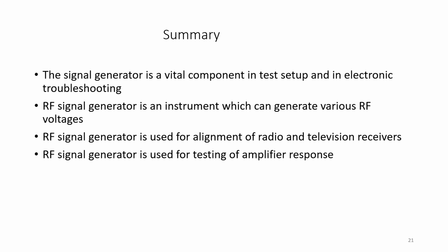So, when we say that the oscillator generates a signal, it is important to note that no energy is created. It is simply converted from a DC source into AC energy at some specific frequency. There are various types of signal generators, but several requirements are common to all types. The frequency of the signal should be known and stable. The amplitude should be controllable from very small to relatively large values. Finally, the signal should be distortion free.